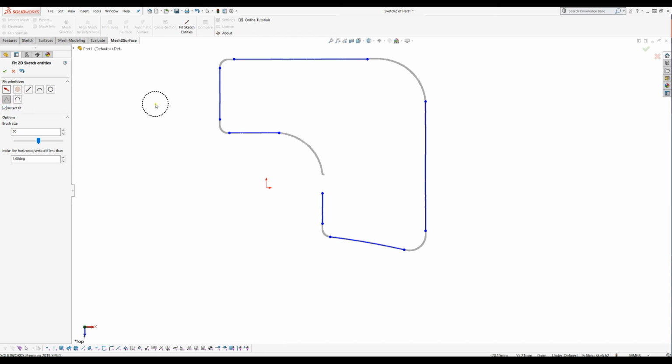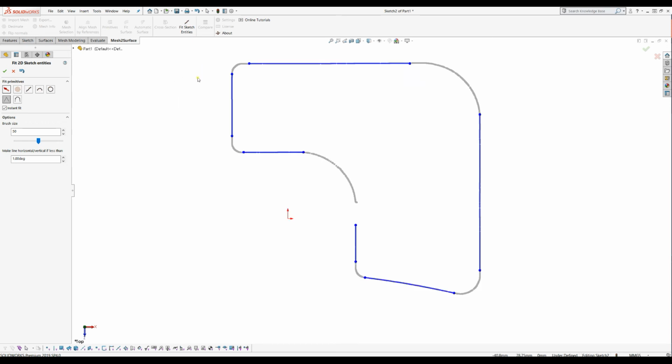The first one is for connecting and intersecting two primitives. It works in the same way as the brushing. You just need to hold your left mouse button and move. And once you get over a point, you see that it's highlighted, and it expects that you brush the second one. And once I get the other one, you see that it actually extends them and intersects. This is not limited to line and line only, but it also works on line and arcs. It doesn't work if you have circles. For circles, you need to use the standard SolidWorks tools to intersect.